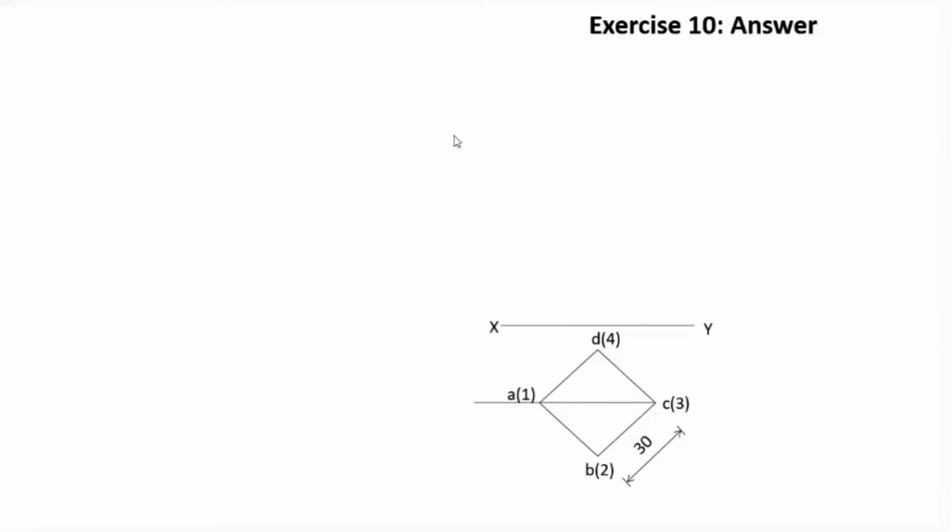So obviously this 40 mm length will be the edges generated by cutting the vertical faces, the longer faces, and the two 30 mm edges will be the edges generated by sectioning the top face as well as the bottom. So we know that the 30 mm edge will be in the top as well as the bottom.